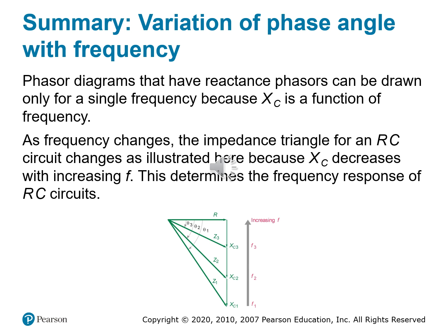And this matters because this visualization shows us the frequency response of the circuit. At low frequencies, capacitive reactance is large, and the circuit is more reactive, voltage lags current more, right? At high frequencies, capacitive reactance shrinks, the phase angle starts compressing, and the circuit acts more resistive. So this behavior makes RC circuits incredibly useful in filters. For instance, high-pass filters rely on this principle to let high-frequency signals through while blocking low frequencies.